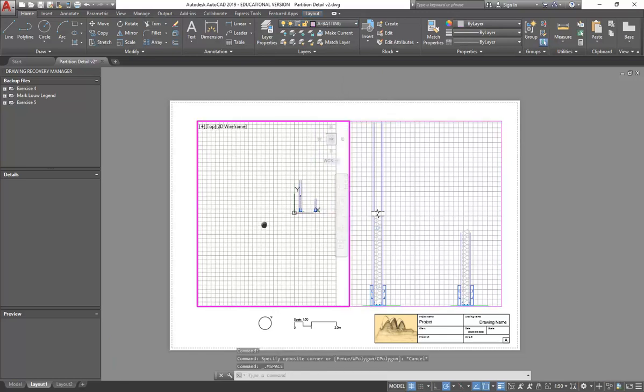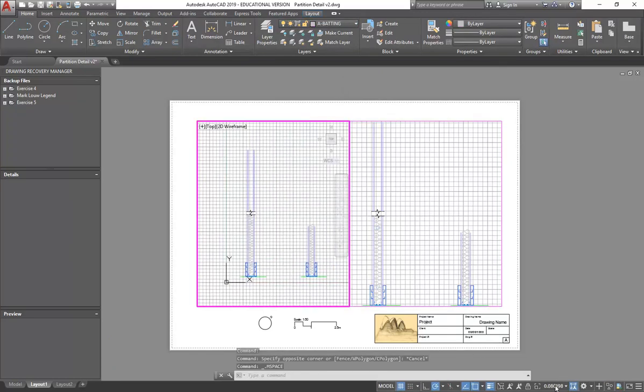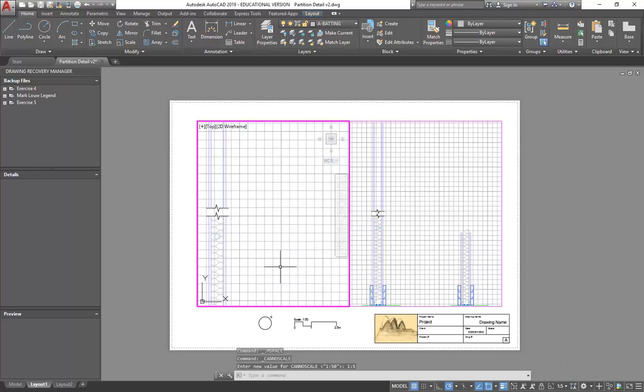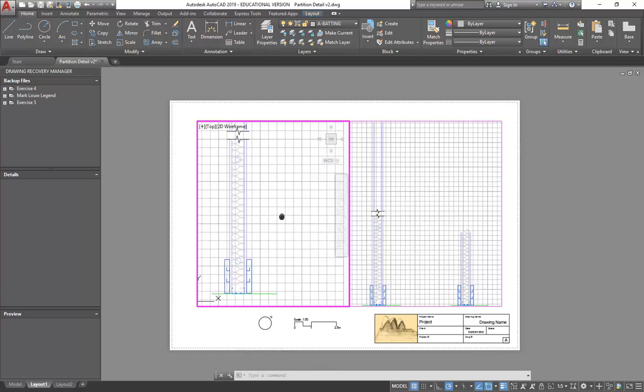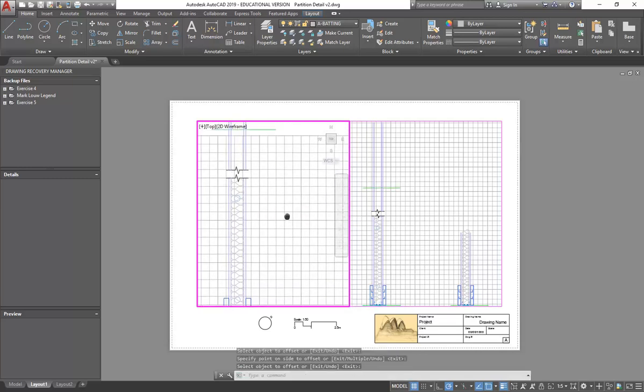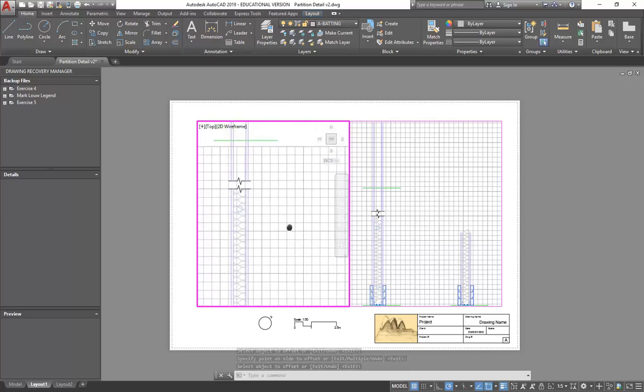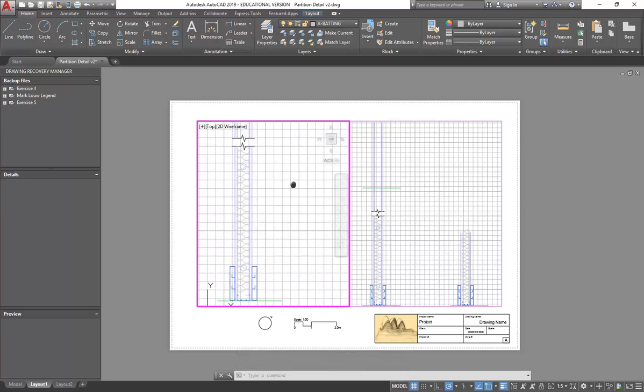And then I want to set the scale of this viewport. Down here we'll go to 1:5, which is the scale you need for the assignment. Then I can pan to get the part of the detail that I need. Now, some of you who are asking about that 1200 height that you might want to show in that detail can start to test that out. If I offset 1200 from my floor line and click above, it's gone outside, so it's up here, and we probably won't be able to fit that at this scale on an A3 page.